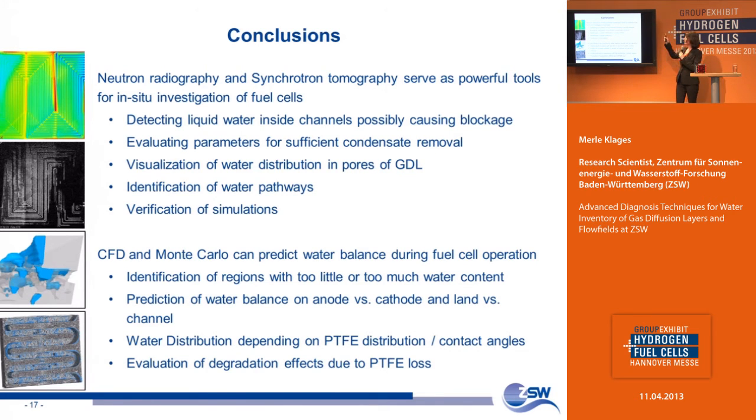We saw the water inside the channels by neutron radiography. We saw the water inside the GDL with synchrotron tomography. And with CFD and Monte Carlo, we could simulate where water is going to be inside the fuel cell, and together with the visualization, we concluded that the simulation itself, the predicted water evolution, is really likely, is near to the real evolution.